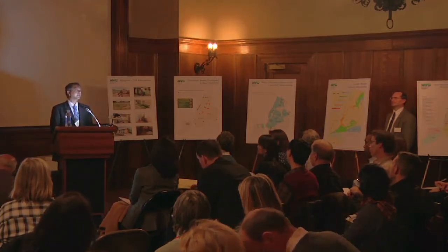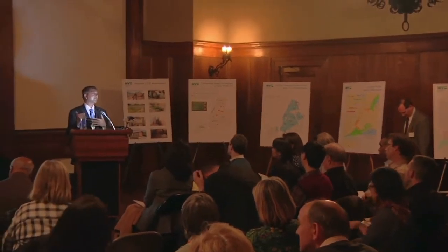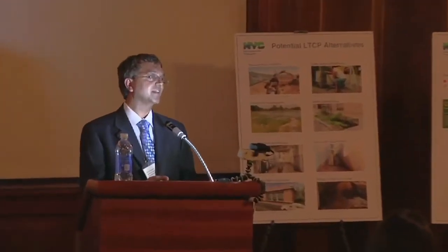One of the key things related to tree canopies is that if it is above impervious area, we are treating that as an impervious area. So we are creating extra runoff than what can be in the real world, which is kind of on the conservative side.